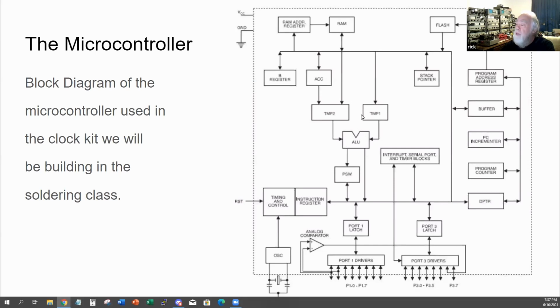If you have temporary data from a calculation, it comes out of the arithmetic logic unit and goes up to the RAM address that's specified when you write to the RAM. So the actual address would go to this register here, and then it would address the RAM, and from that random access memory, that data would be read and put back onto the system bus and used by whatever component needed it.